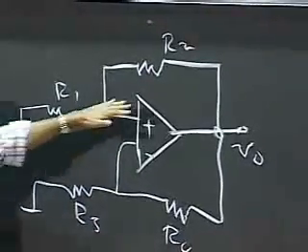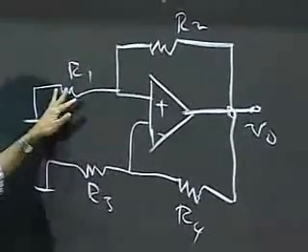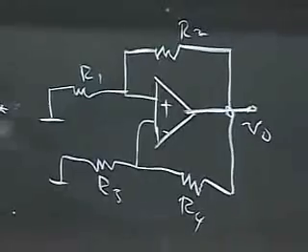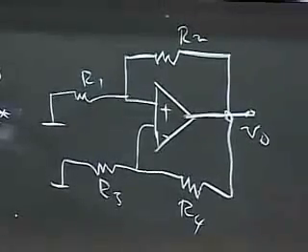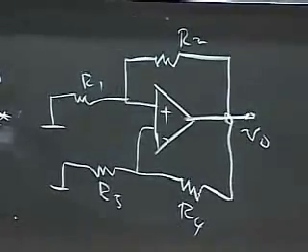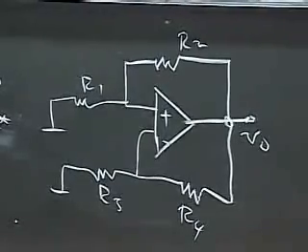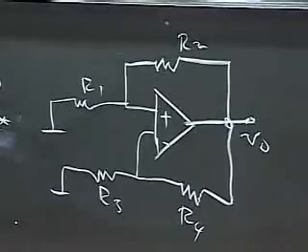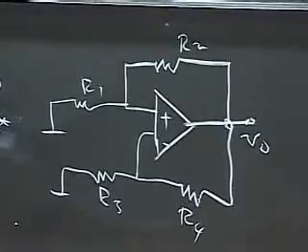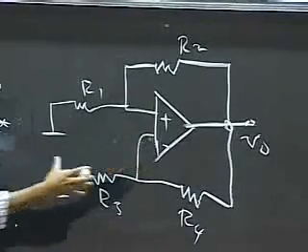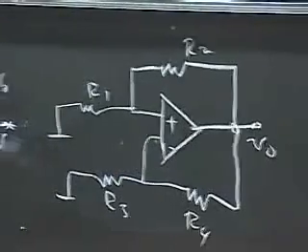Okay, all I'm doing is applying both a positive feedback through R2 and R1 and negative feedback through R4 and R3 and representing the dynamics of the op-amp and then standing back and seeing, all right, let's see what happens to you. Okay, so I'm sticking positive feedback, negative feedback, the dynamics of the op-amp here, and let's see what happens. Okay? So what I'd like to do is impose this circuit on top of this op-amp model.